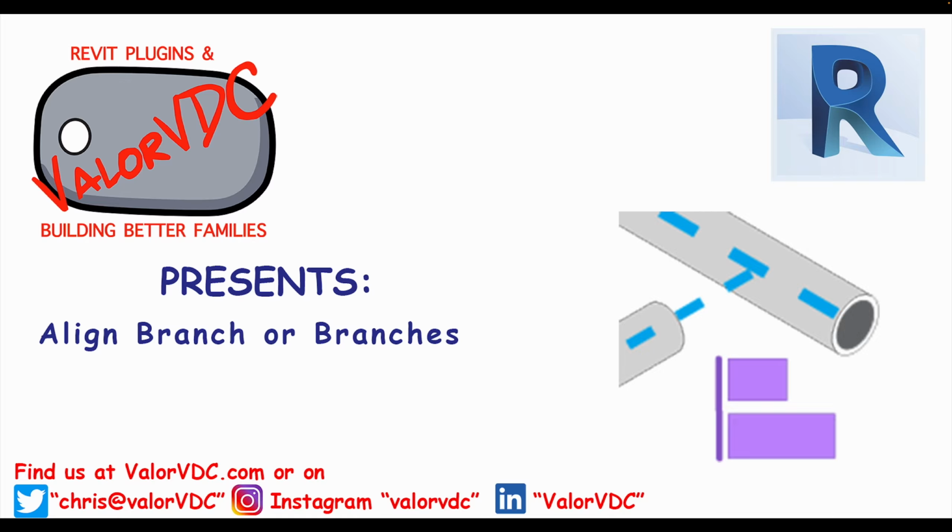Today I'd like to talk about a tool in our suite called Align Branch. What it does is align any branch pipe, conduit, duct, or cable tray with the main run, or any run you select. So if you have two pipes at different elevations and you want them aligned so you can join them with a T or an elbow, you can. Without further ado, let's jump into Revit, and I will show you how this is done.